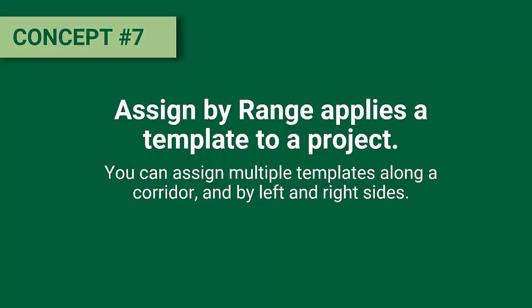Okay, concept 7. Assign by range applies a template to a project. So as we saw, the template editor is our sandbox, and anything we do in there doesn't apply it to our project. So we're going to go in and take a look at how assign by range applies a template to our project. And as a sub-bullet to this, you can assign multiple templates along a corridor and by left and right sides.